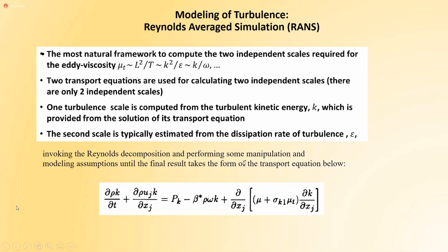Invoking the Reynolds decomposition, performing manipulations. What you see here is not the exact turbulent kinetic energy equation. Okay, we can derive it. It's easy to get the kinetic energy. If it's specific energy, you just multiply the velocity equation by a perturbative velocity.